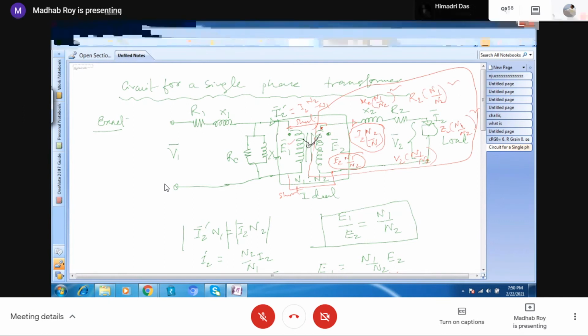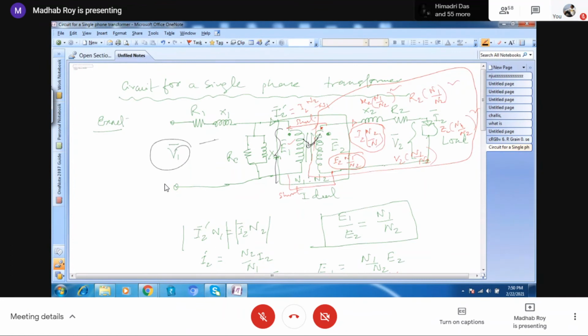Okay. So the main problem is that, in a transformer, we are discussing from the interview point of view, a voltage is applied across this. Suppose you have a voltage of 1 or 2 kilovolt. So you should put a material so that there will be some insulation for this 2 kilovolt. Otherwise, there will be a short circuit across this. So you should not use such material which can put a short circuit around the coil. That's why the main problem is that we cannot select the diamagnetic material also. That's not a good insulating material. So you have to provide some insulating material there. Insulating material means epoxy, resin, paper insulation, and various kinds of insulation you have heard, insulating oil. Those materials will not have an infinite reluctance.